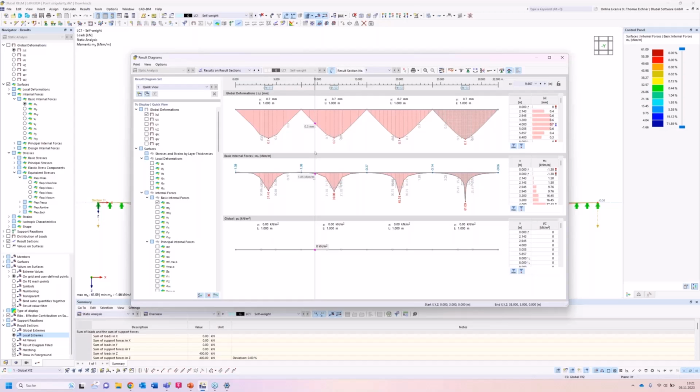So there's space to redistribute forces. That means when you locate your reinforcement with square centimeters per meter, in most cases, you can inspect the results on a meter, and you can mostly smooth the values on a meter. Okay, so that's one possibility with the smoothing ranges.